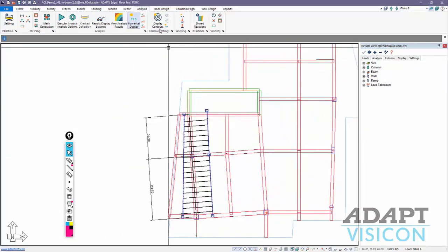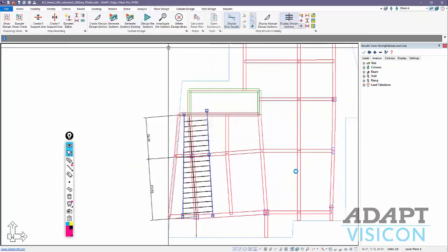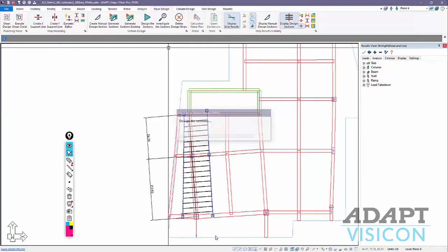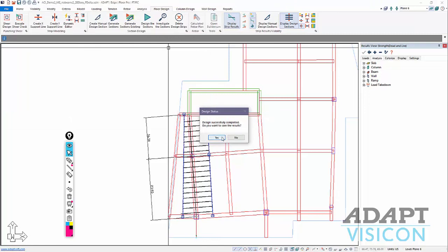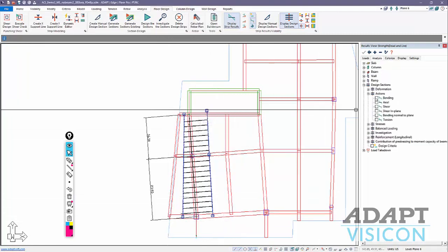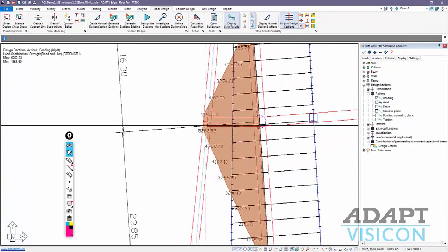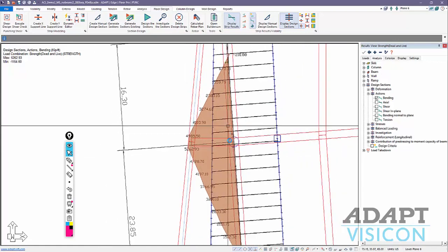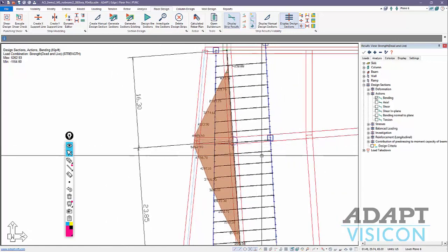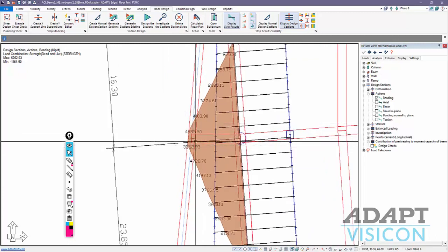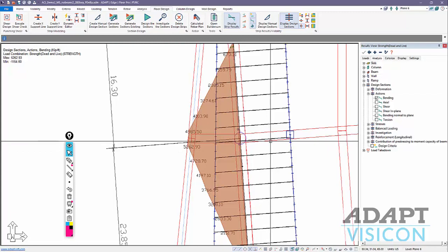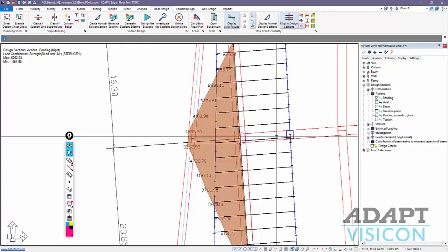And we're going to design the sections at this level. Again, important distinction, we did not have to reanalyze the single level. If we go now to the bending actions again for strength, dead and live, for example, we have a little bit different moment in this. The secondary actions from the PT may not be contributing much to the moment, so that will affect the results here somewhat, because this strength combination includes the hyperstatic actions from post-tensioning.